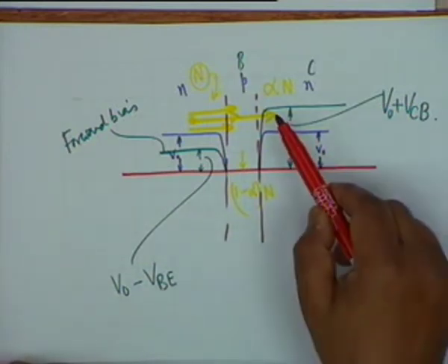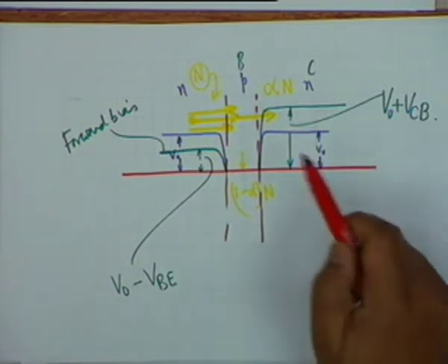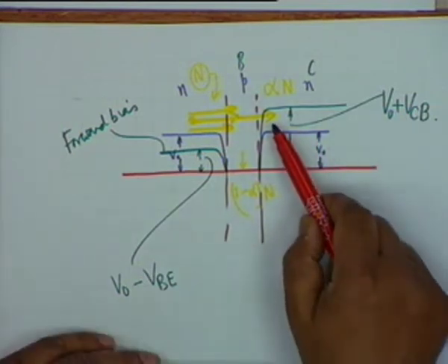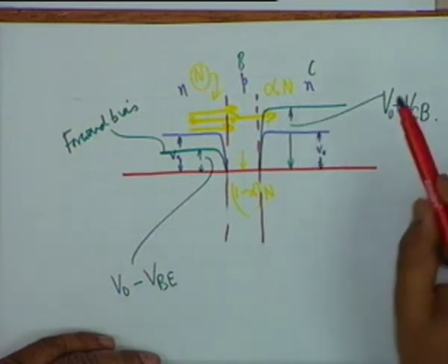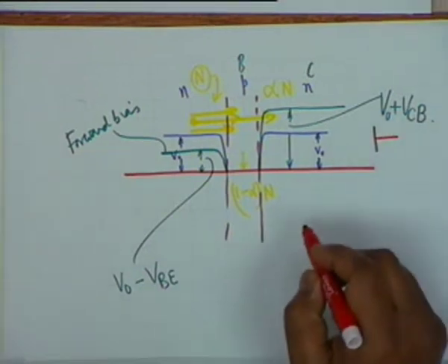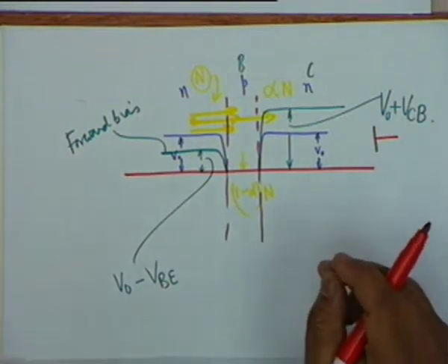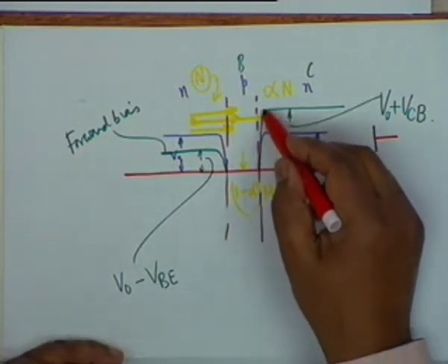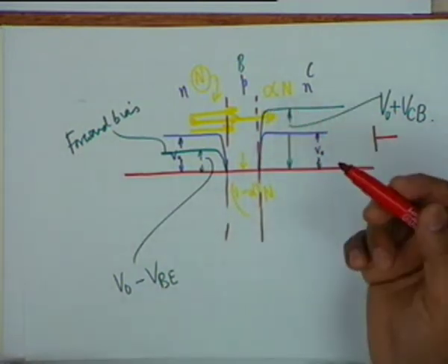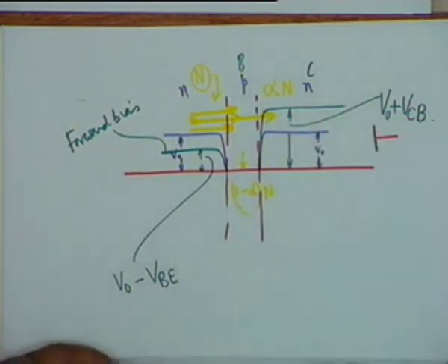They go up the potential barrier. After all, these are electrons, and this is reverse biased. In other words, there is a battery with a positive terminal here which is trying to attract the electrons, and therefore they are encouraged to climb this barrier. Electrons can climb very easily and pass to the battery.